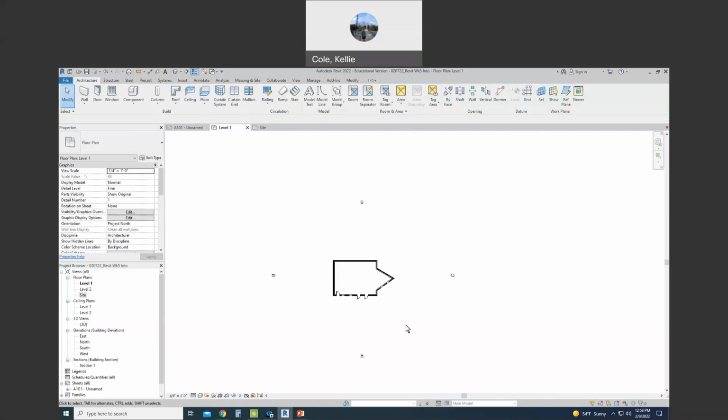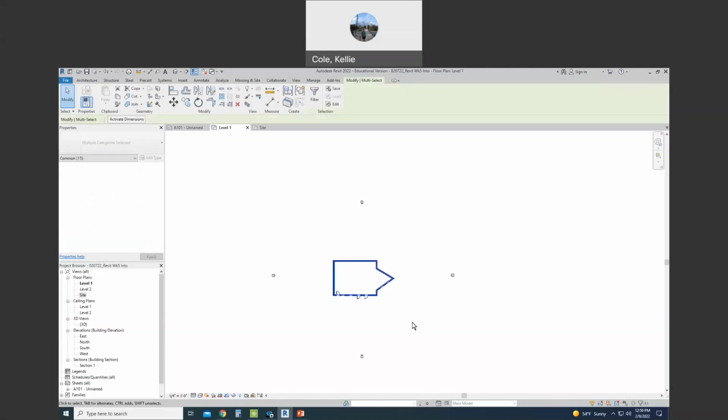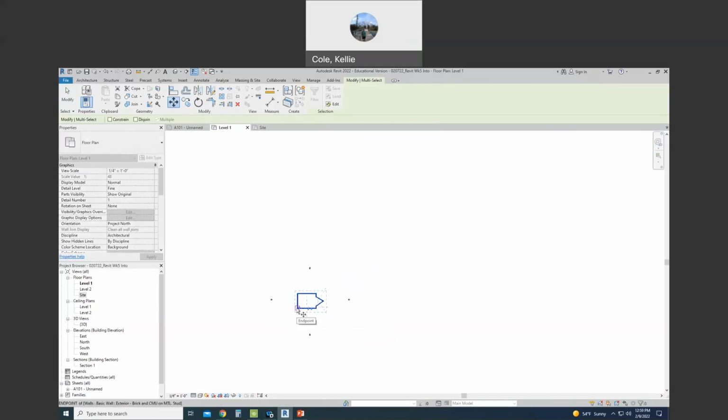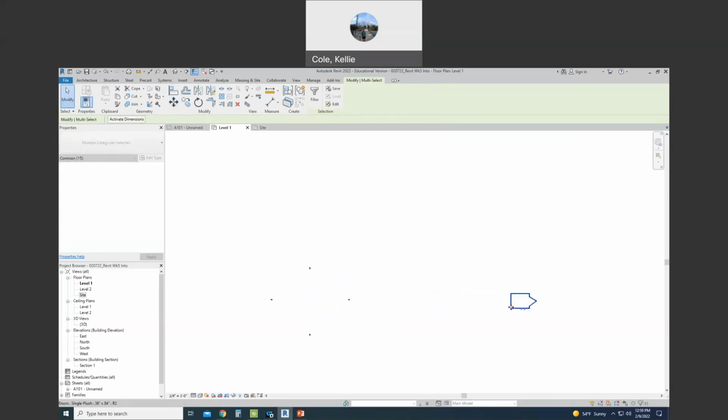Because I've already pulled those window views onto my sheet, with the location of the subject being our first house-like structure Monday, we can actually draw in the same area, and then when I want to look at Maya Lin stuff, it will bring up those views of her project instead. Okay, so what I'm going to do is select the whole building and type in MV for move. Click an endpoint and drag the house out about 500 feet.